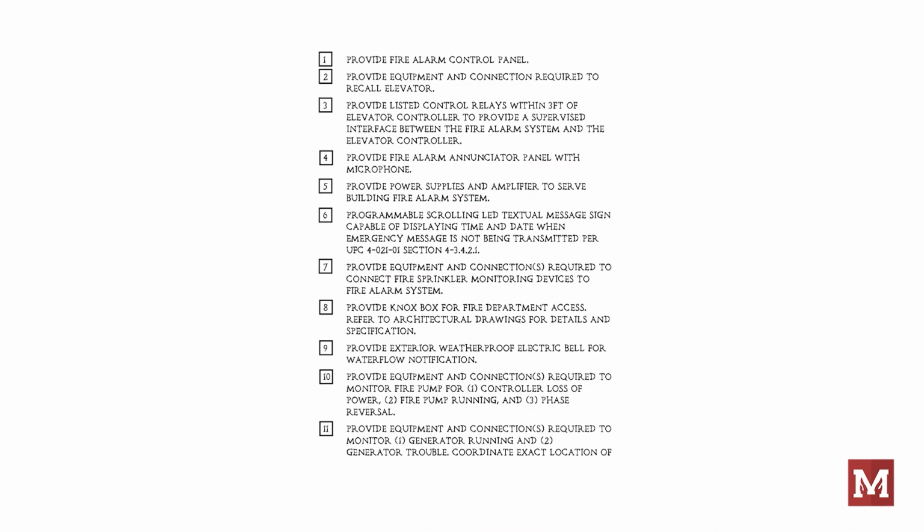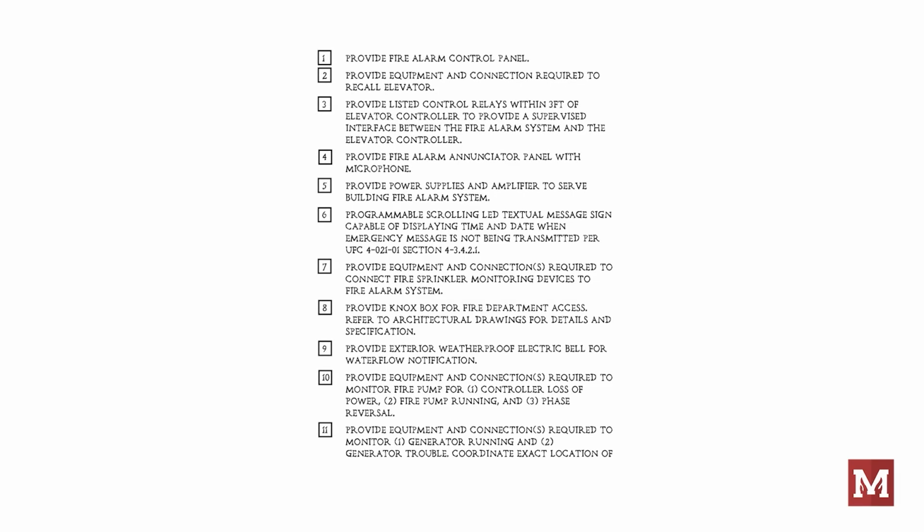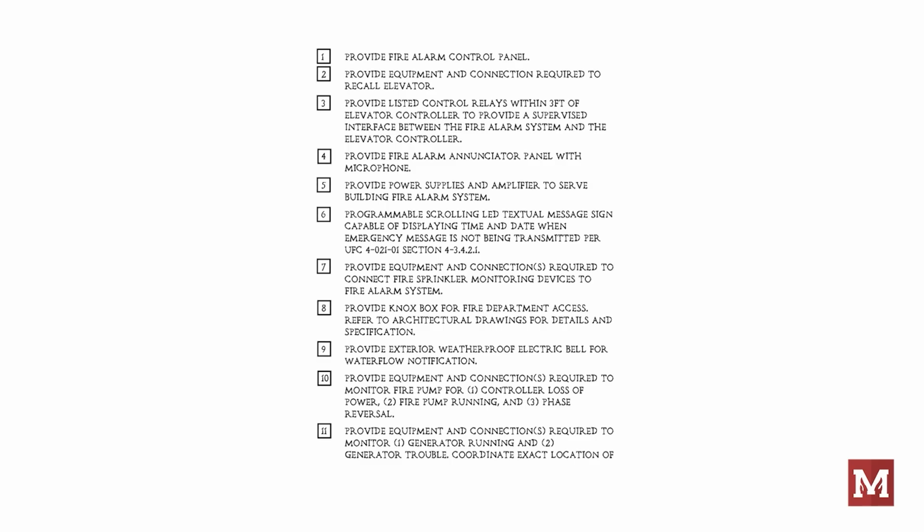You'll find pockets of notes and symbols throughout the building plans. Notes typically refer to direct text, whereas keyed notes usually involve symbols that are clarified by a legend on the same page. An example of this would be a typical sprinkler legend on the automatic sprinkler plans.